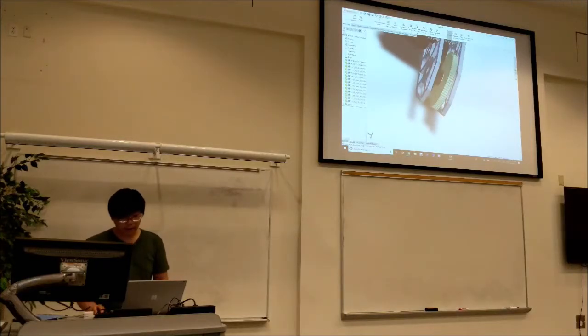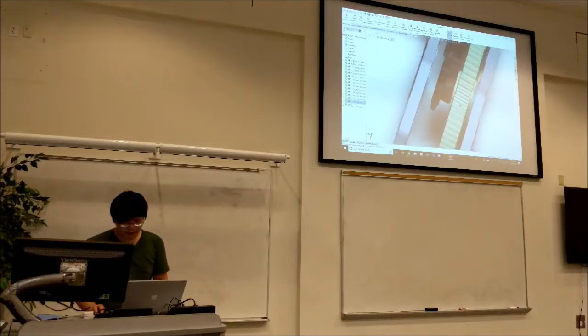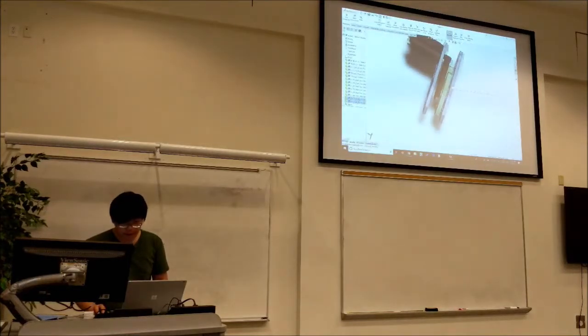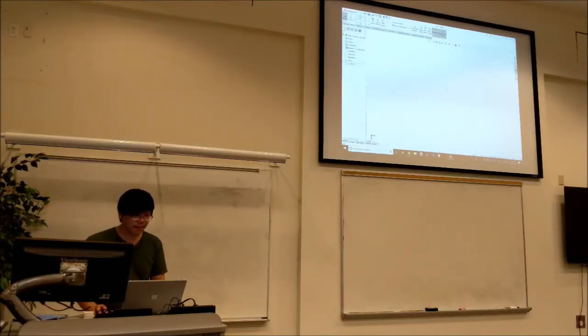So now I'm going to show you how to CAD this shaft. We can measure from here to here to know how long the shaft needs to be. It's 1.121, which doesn't need to be that precise, so we can do 1.12. So we make a new part. This is going to look weird at first, but it makes it nice to change the shaft later on. Then you draw an infinite length line there.